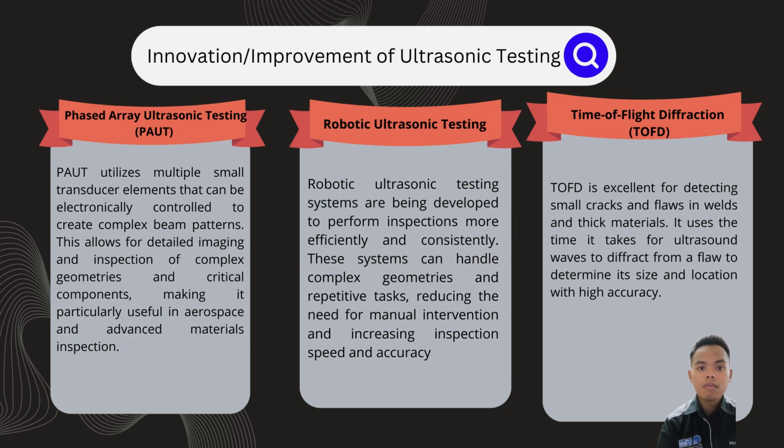After that, time of flight diffraction can give results immediately and allows quick inspection. Time of flight diffraction is sensitive to all flaw types, including cracks, slag and lack of fusion. And then lastly, it is able to create accurate sizing of defects.